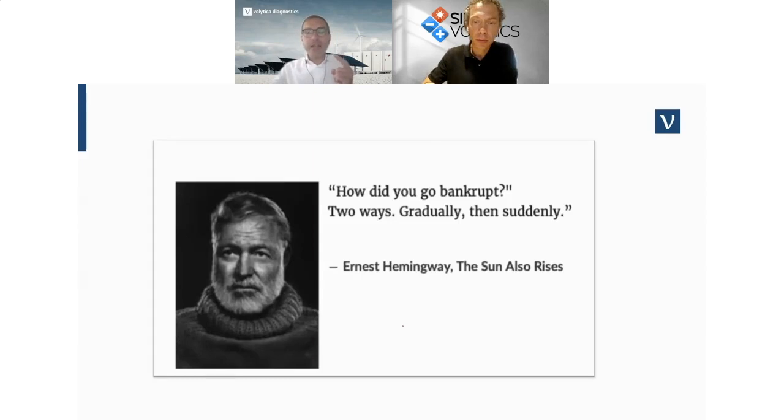Now, when is the end of life? Not the end of warranty. When is end of life? And end of life is, in our opinion, when a battery is not usable for a purpose anymore. When the energy capacity has dropped too low, the efficiency has dropped too low, or very simple, when it just stops working entirely. And when is that? Well, that depends on the use case and not just on a limit like 60, 70 or whatever, 80% SOH.